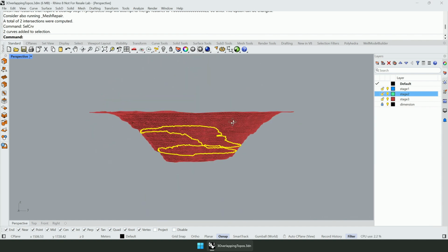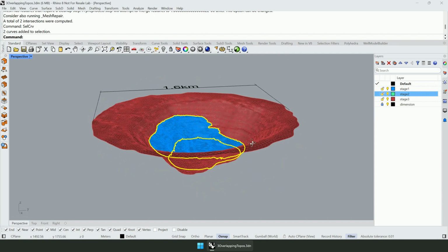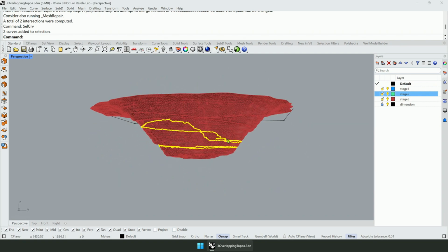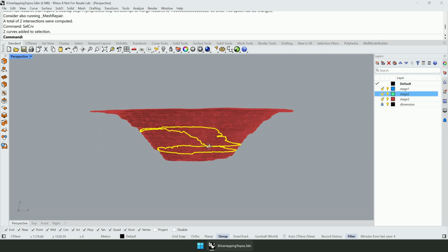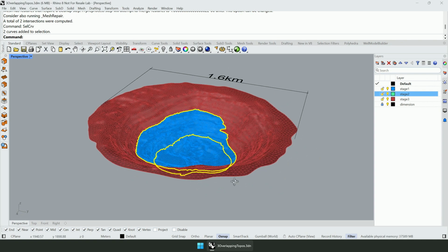This way we basically separated overlapping meshes, and you see that now it's clean topography, and we can easily create closed volume domains in between the excavation stages of this mine, and maybe a closed volume domain above and below. So this demonstrates how gCollapse works, and now let's switch to the next topic.